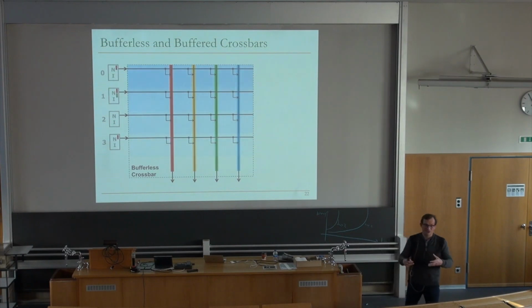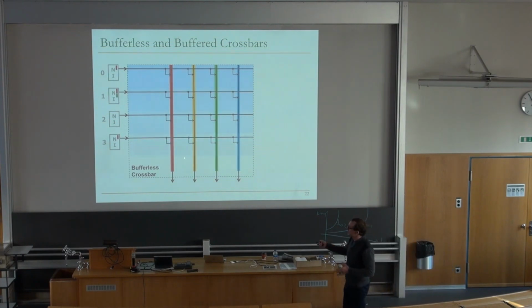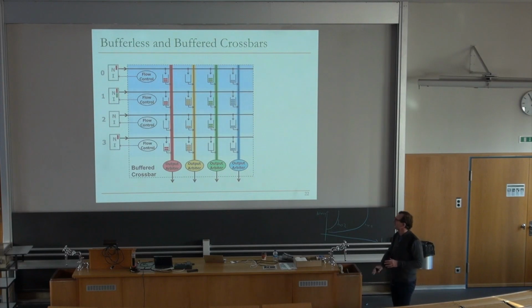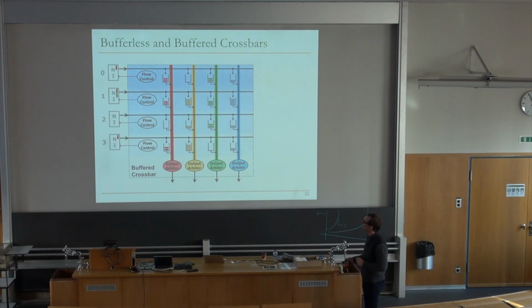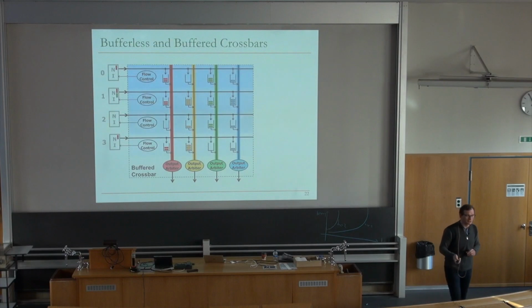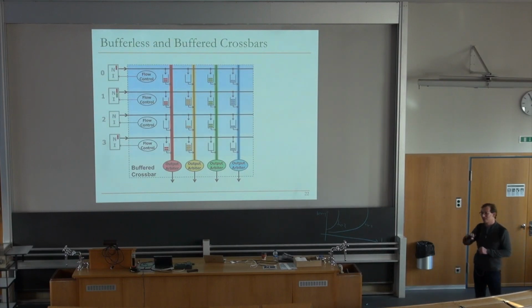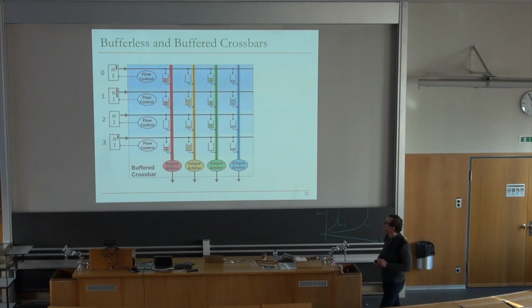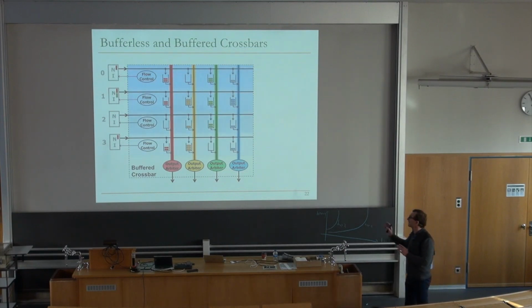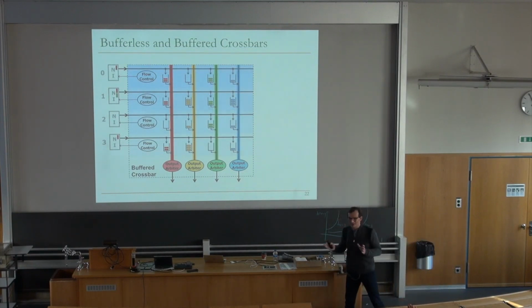Flow control is really in the arbitration mechanism over here, right? But the arbitration mechanism may not be as easy over here. Here, the arbitration mechanism is a little bit more relaxed, because you have buffers and you've latched everything, and then you have the full cycle to do the arbitration. But now you have buffers, a lot of buffers perhaps, and also you need to have flow control to manage the buffers. So this is the buffer management overhead, and that adds more cycles, as we will see. Okay, so even the crossbar, something as simple as a crossbar, requires thought to build, and also a lot of engineering. And you can think of a crossbar as very simple, I think.